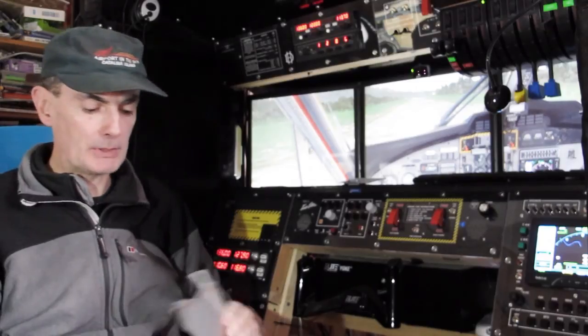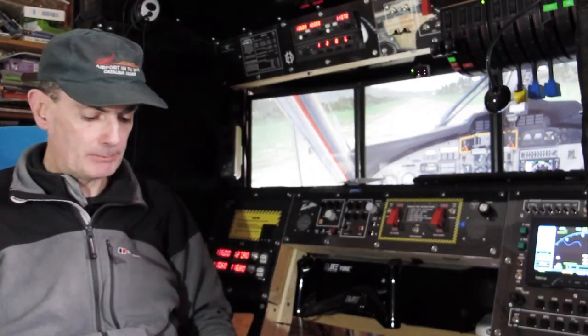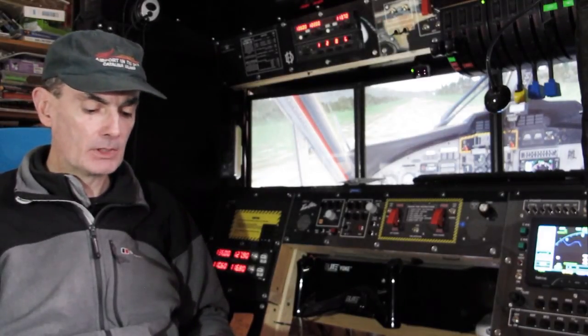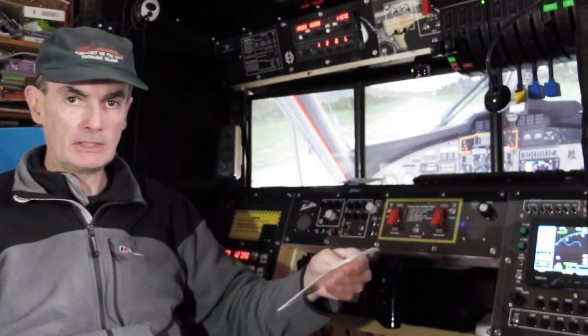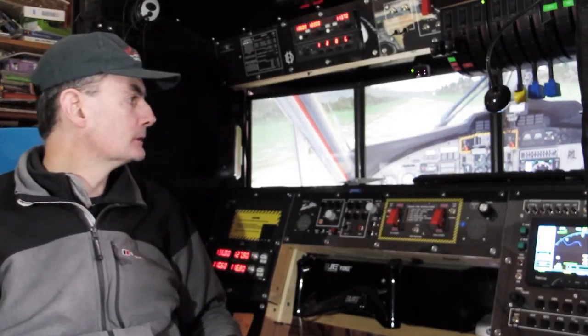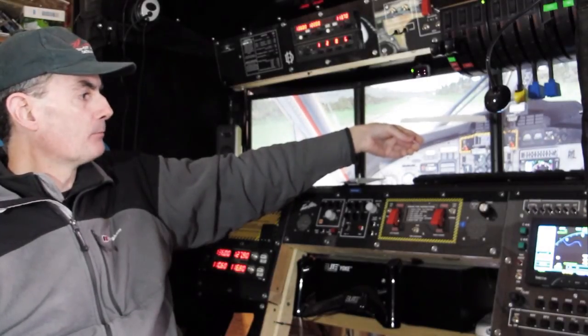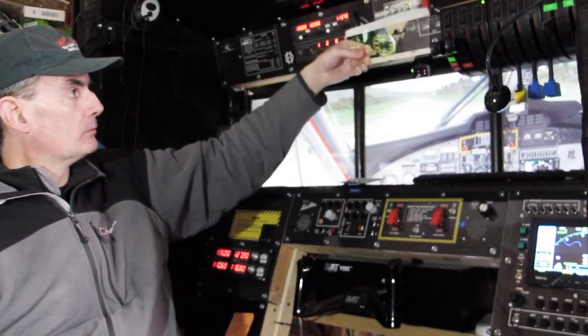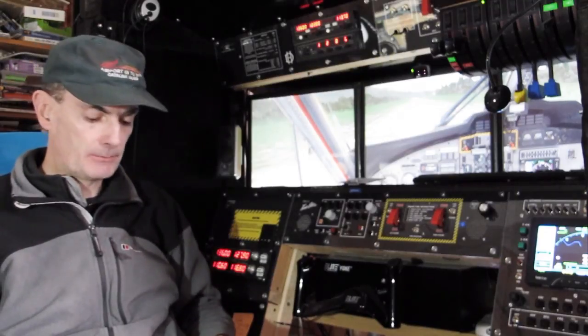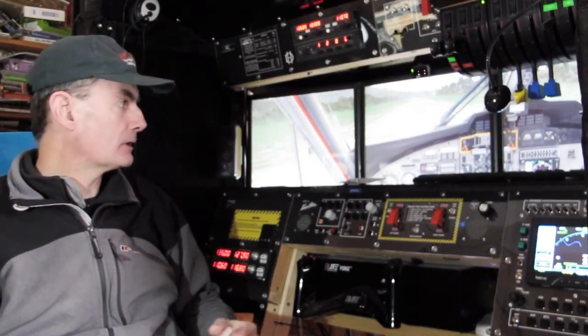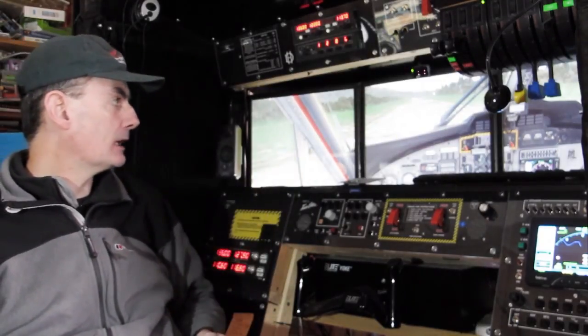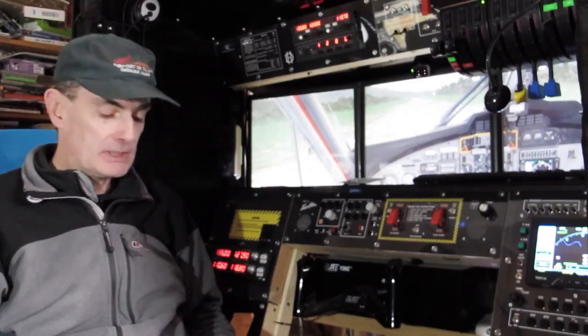Now there's a couple of problems with that. The main immediate problem with that is in practice the contrast of the display once it's reflected off this material is simply not enough. It's just washed out. If it's suspended in front of a dark piece of the panel, or indeed one of my own dark coloured hardware panels, it's very readable and very satisfactory. But once it's in front of sky or terrain, outside the window view, which is exactly where you need it of course, the contrast isn't sufficient.